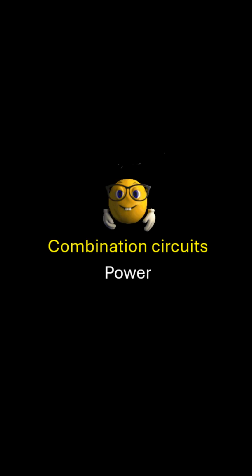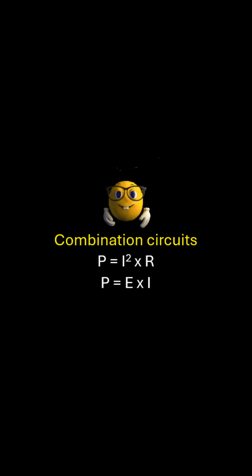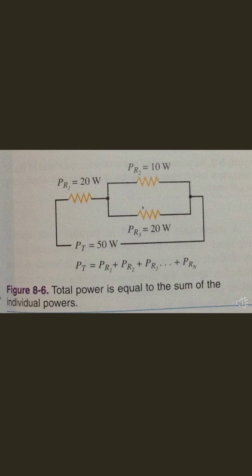Power in a combination circuit. Power in a combination circuit can be calculated by using either the formula P equals I squared times R, or power equals current squared times resistance, or the formula P equals voltage times current. These formulas can be used for each individual resistance or for the circuit as a whole. Total power in a combination circuit is equal to the sum of the individual wattages, regardless of whether they are connected in series or in parallel. Figure 8-6 illustrates how power is determined in a combination circuit.